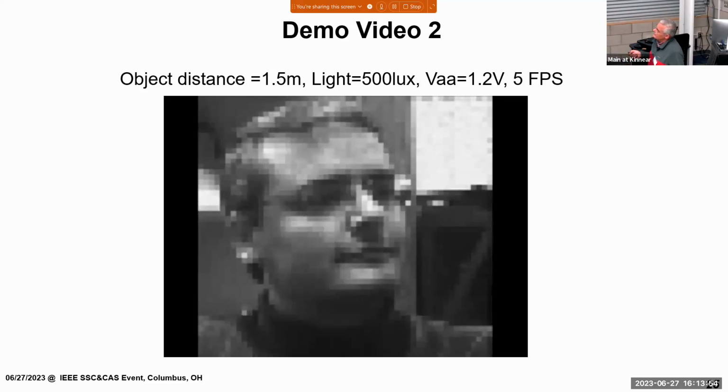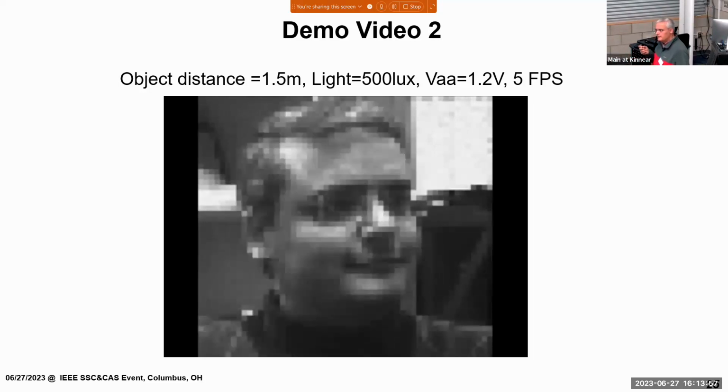If you ask blind people, I'm going to implant something in your eyes, what do you need? Most of them say, I need 1 pixel, only 1 pixel so that I can see light and dark. 2 or 4 pixels is a luxury for them. 54 by 50 is huge, because after 32 by 32 you start seeing intelligence in the images you capture. Still, 54 by 50 consuming 14 microwatts, and harvesting that much energy over 8 seconds, is still something to be improved.